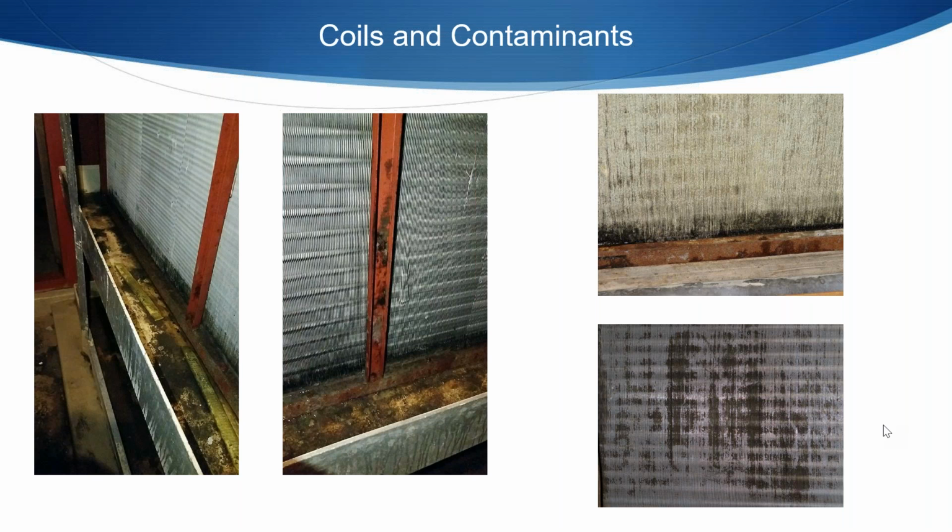So when people think about UV, this is traditionally what they're thinking of: coil cleaning. Even for me, up until I took a job with UVDI just a couple of months before the pandemic, I had only clicked it on the box in a manufacturer software to try to provide some level of coil cleaning. So this is still a very important reason to have UV. Being from the mountains, on the dry side of the mountains, I didn't really concern myself too much. I didn't see a lot of applications with tons and tons of mold growth in my dry climate. But what I did not account for was the biofilm growth that you can't really see, which is happening all the time when we have any condensation on a surface like this.